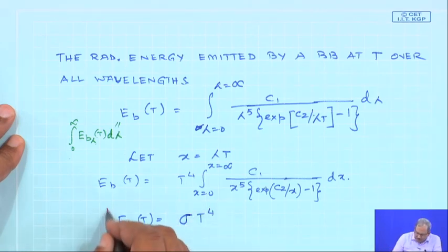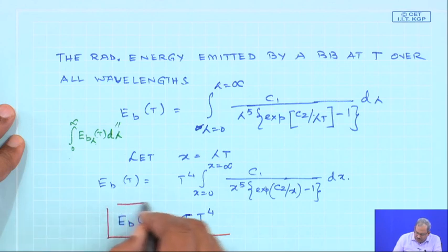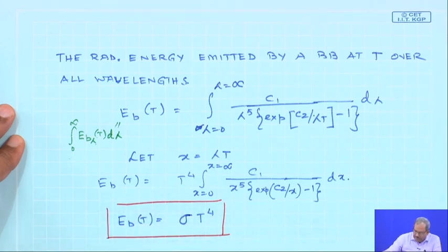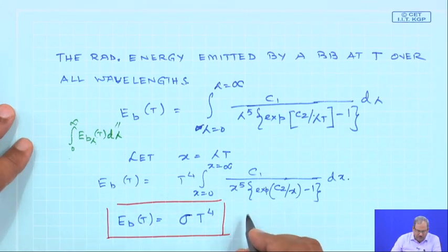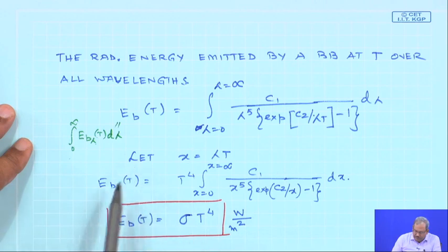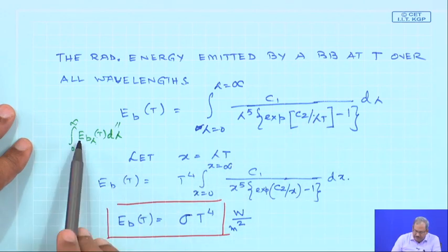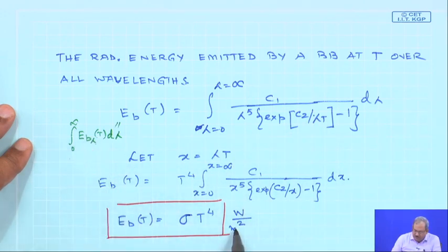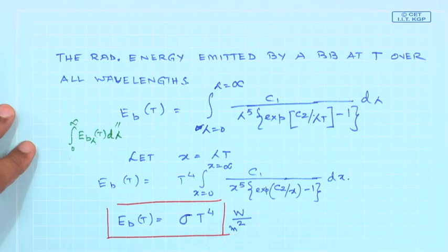So, this is probably the most common radiation expression that you have seen before, and this is watt per meter square. The unit for E b lambda t is watt per meter square per unit wavelength, which is in micron. Since you have integrated it over all possible wavelengths, this one will not have the micron over here; it is simply watt per meter square.